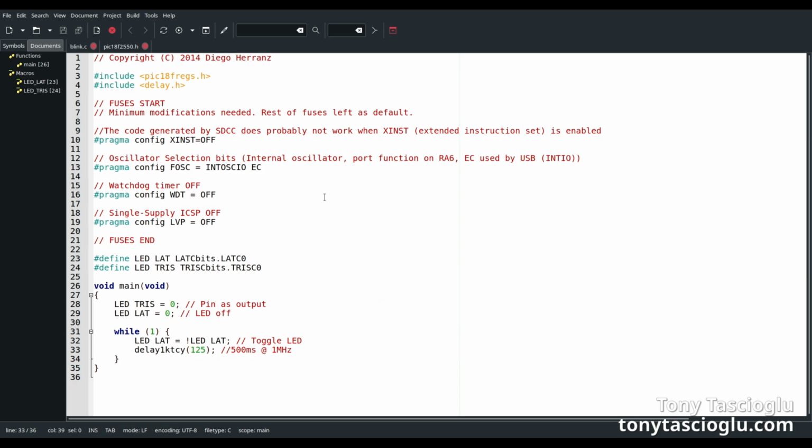In this case, our LED is set to be on pin C0, as it is set by pin LATC and TRISC. So we will use port C0. You can use any of the other ports that support functioning as a digital output as well. You can go with port B0, A0, depending on which pins they map to on your IC. If we're going to be using multiple devices, you might want to be strategic and save the ports that can be used for other functionalities, such as I2C for that.